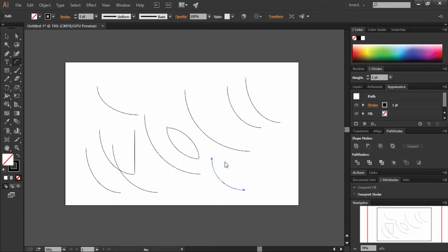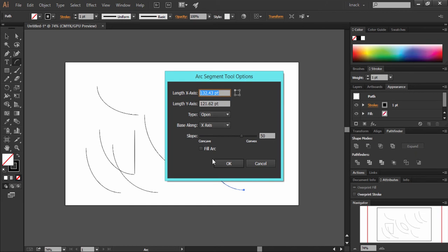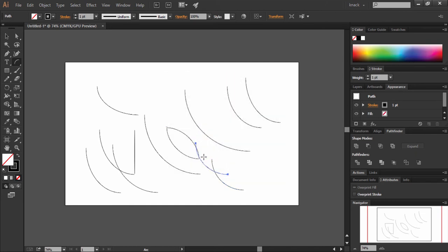The resultant line according to the above values will originate from the point of click. But here is one thing to notice. If you want to draw a center outward arc with the dialog box, then before I click once to open the dialog box, I will press the Alt key. Now if I click OK, then a center outward arc will be drawn.